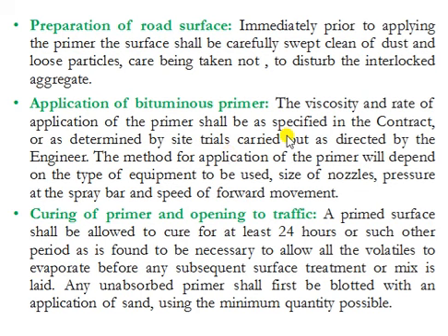a primed surface shall not be open to traffic other than that necessary to lay the next course. A very thin layer of clean sand may be applied to the surface of the primer to prevent the primer picking up under the wheels of the paver and the trucks delivering bituminous material to the paver.